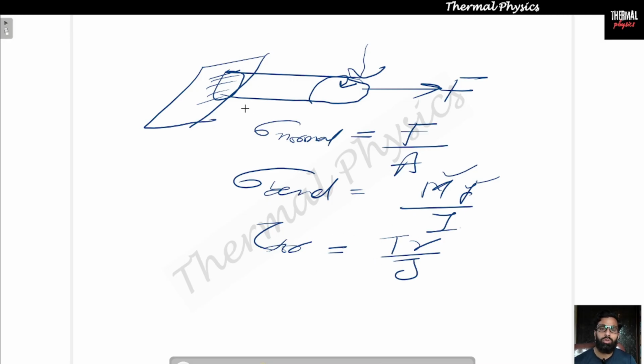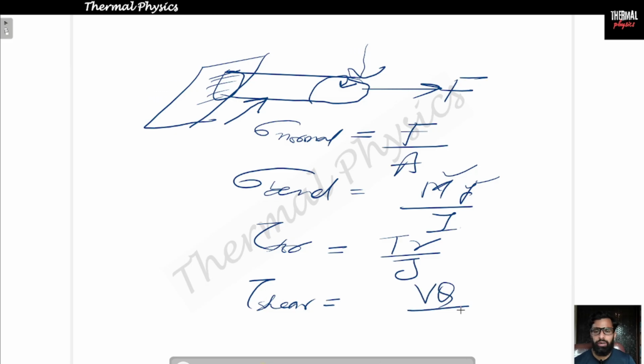And suppose also a load is acting perpendicular to the axis, which is trying to break it because it is fixed on the other end. So, shear stress. We will calculate shear stress using the formula VQ divided by Ib, where V is the shear force, Q is the first moment of area, which means area times the distance, b is the width, and I is the moment of inertia. So these are the various kinds of stresses that we can theoretically calculate using these formulae.